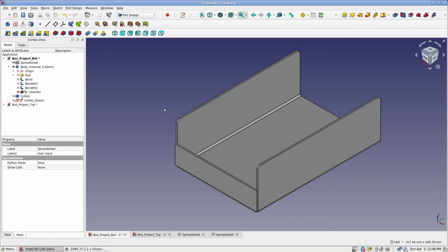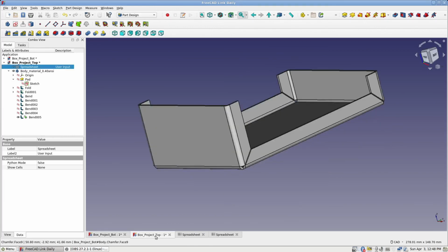So that's it. I hope you've enjoyed these models. I hope they're helpful. This is a nice little box. You can put electronics in here. You can use this component tab for switch, fuse, lights, grommets to bring wires in. You can also add fasteners on the side. Just make sure that this metal here provides enough so you can drill a hole in here. I used PEM fasteners and 6-32 machine screws, and it's in the video that shows how this box is actually made. So I've done that, but you've got a variety of options that you can use for the fasteners.